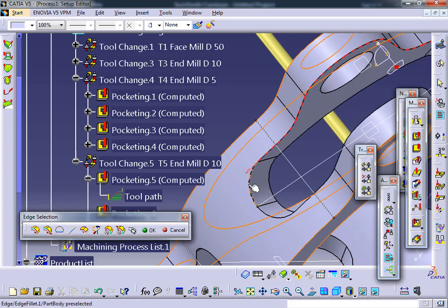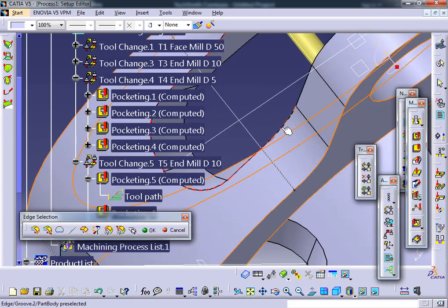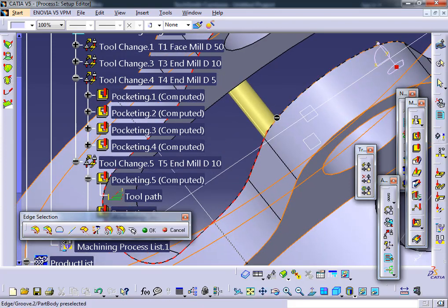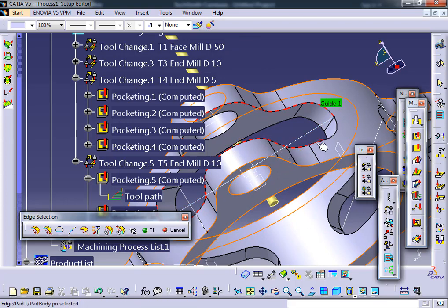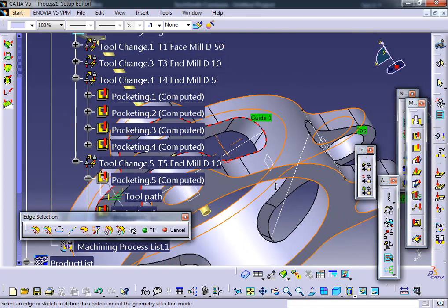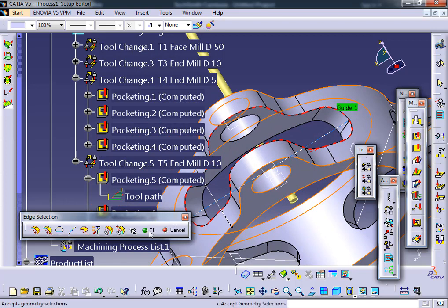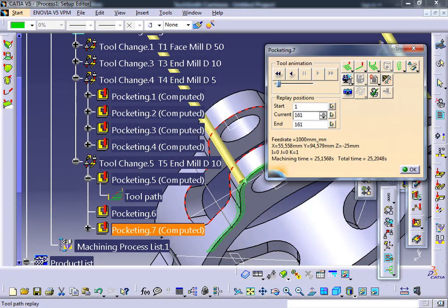All of this needs a lot of experience in order to analyze the results correctly before going to the final step, which is to obtain the G code and insert it in the machine, a CNC machine or similar. After that, the operator will just give a stock to this machine and click start, and the machine will follow the G code, and if all is good, we'll obtain the right parts.